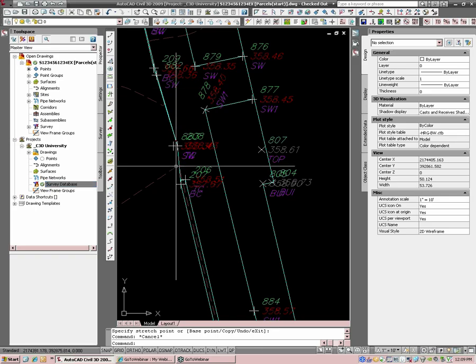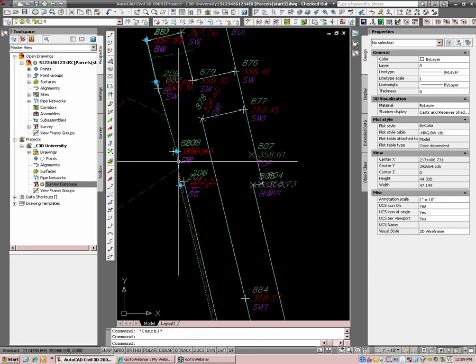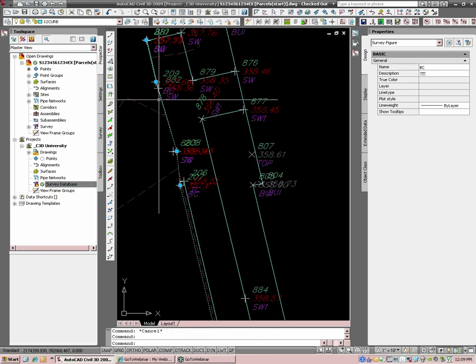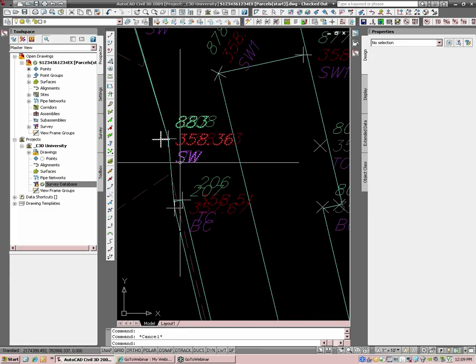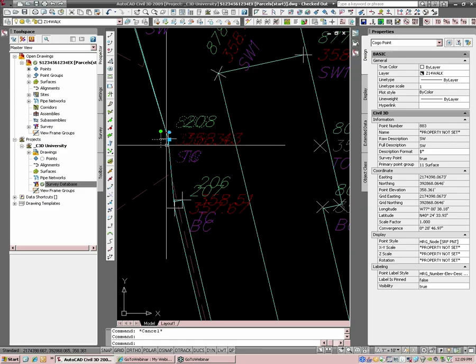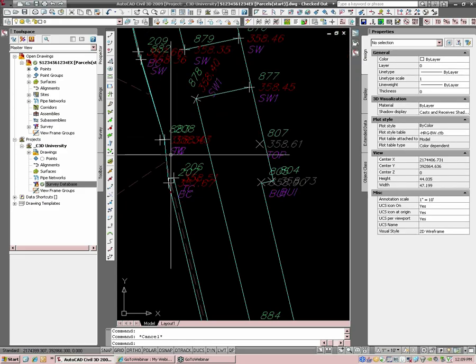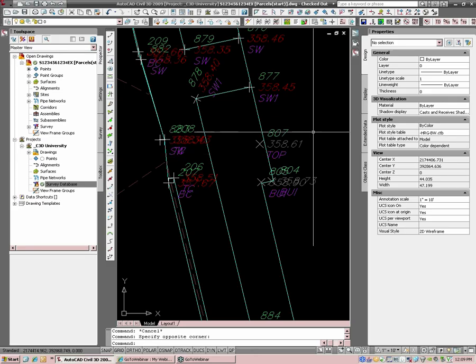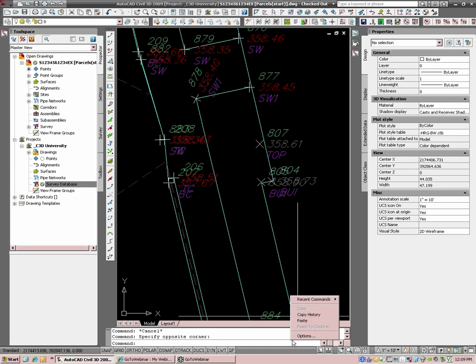Now this one curb line here, the way it pulled across here, it's not exactly correct. We really want this bottom of curb line to tie into the bottom of sidewalk here. So what we're going to do to edit that, it's real simple. All you need to do is make sure that your Z-lock is turned off, which you can do by going into Options in AutoCAD.